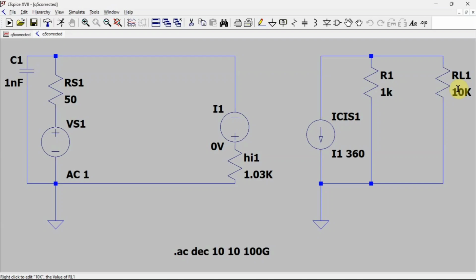That means you can make the resistor a parameter and change the value. You can either give specific values, or give a range of values with a particular gap. Let's say we need 1k, 2k, 3k. This is what step parameter does.